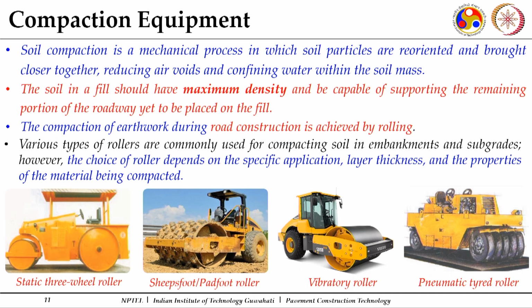Now, with this particular one, there comes the requirement. Once you have brought the soil, you have dumped the soil, you have spread the soil with the help of the dozers, with the help of your graders, now you need to compact it. I haven't discussed the water tankers which need to sprinkle water, because we discussed that in the previous lecture. Once the soil is spread, you put water over it through water tankers having a proper sprinkling arrangement, so that there is a uniform distribution of water, and then you can mix it. You can mix it with the use of rippers also.